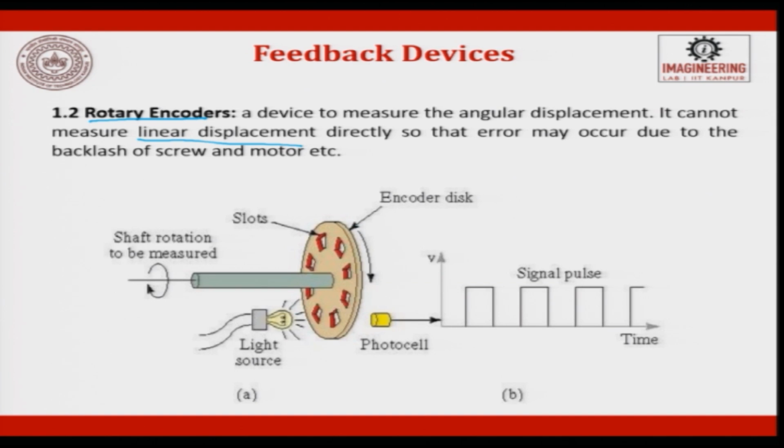In the encoder, you will have an encoder disc which has opaque and transparent slots. Through these transparent slots, the light is passed through. The light that passes through is collected by a photodetector. The photodetector gives pulses. I count the pulses and then find out the resolution, or the movement that has happened. This is attached to the ball screw, as you can see here.